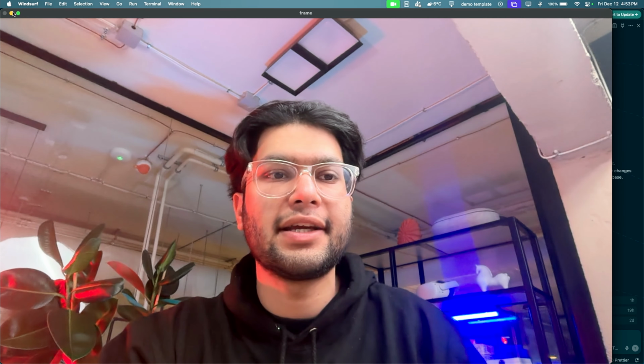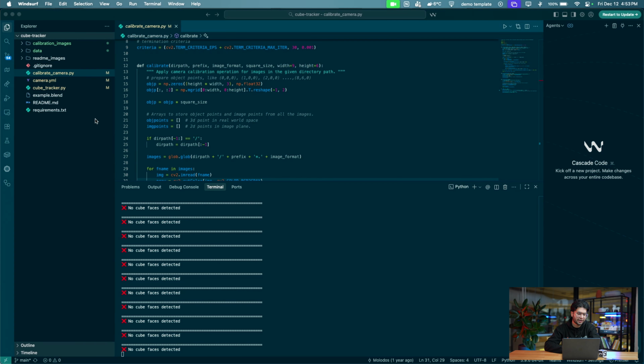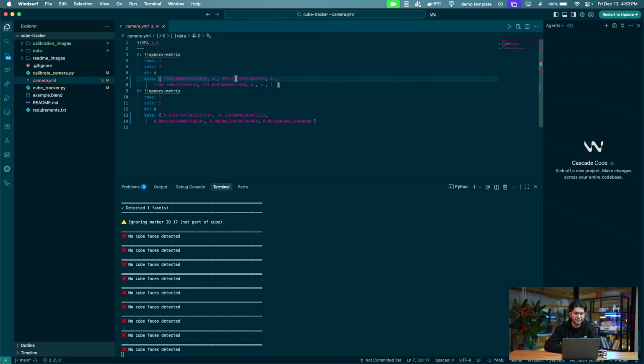So before doing these things, it was just the camera guessing the cube in the space, just like a 2D guesser. But after calibrating the camera, we are giving the camera a kind of prescription: this is your focal length, this is your center X, center Y. Before giving us the exact position of the cube, you have to calculate these things. Before using those, we were just guessing, and now we have a more exact position of our cube. This was the one thing that I worked on this week.